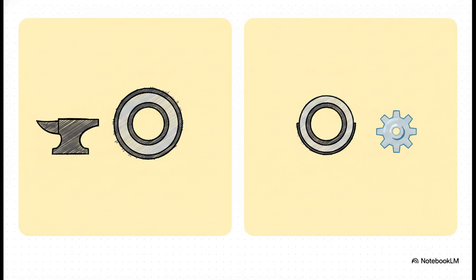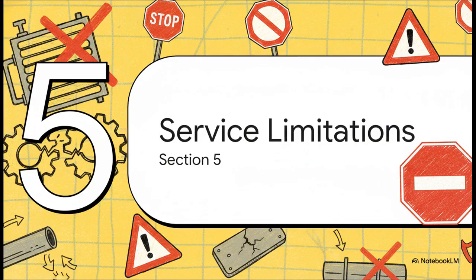Now, if we swap over to cast iron, specifically under Section 1.53, we see the exact same fractional contrast that we just saw with carbon steel. Cast iron pressure parts for those severe Class R applications must have a 1/8 inch allowance under R 1.53. For Class C and B, it drops right down to a 1/16 inch allowance. It's just a perfect illustration of how TEMA purposefully scales structural durability to directly match the intended severity of the application.